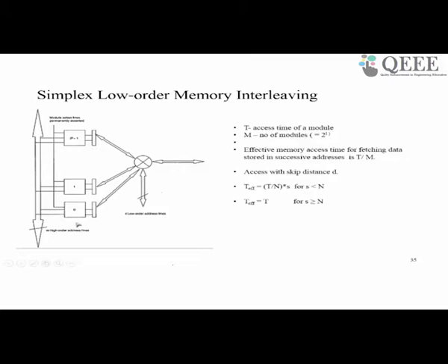Then what will happen is, let us say the address is 0 on these m lines. If all the bits are zeros, then we are selecting the address 0 in each of these modules: address 0 in module 0, address 0 in module 1, and all the way up to address 0 in module 2 power L minus 1. Then all these modules are selected and the read command is given. So all these modules will start fetching the content of the 0th location in parallel.